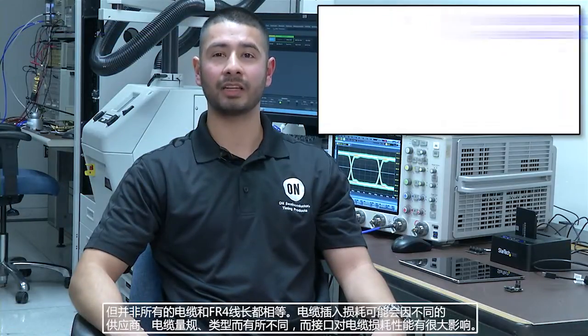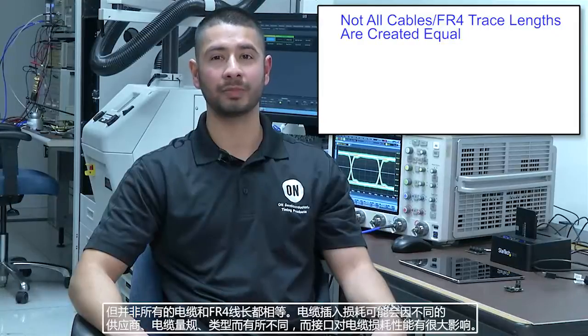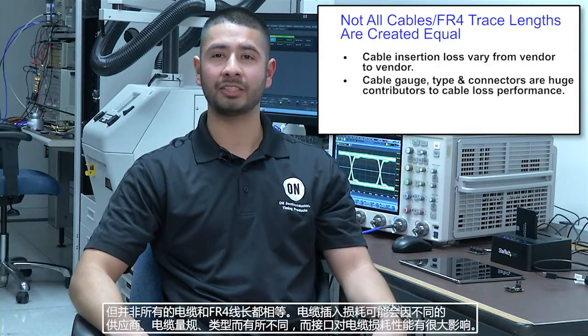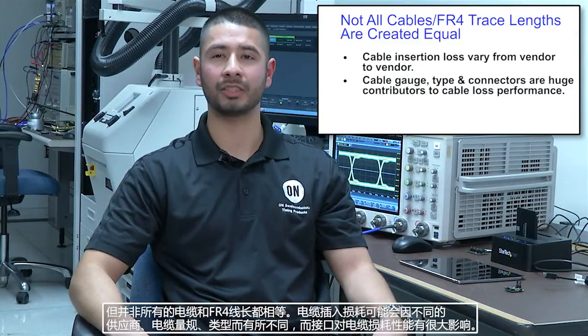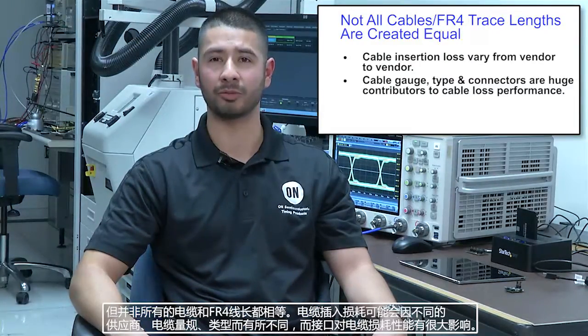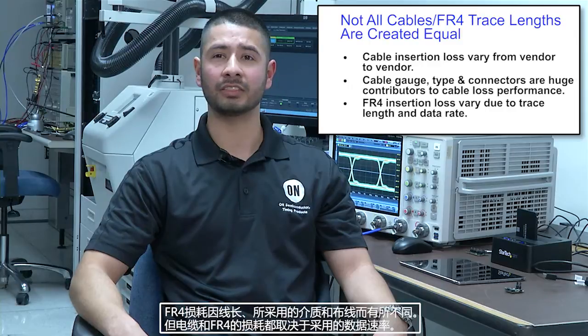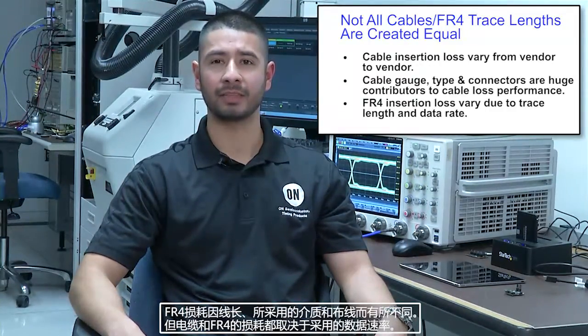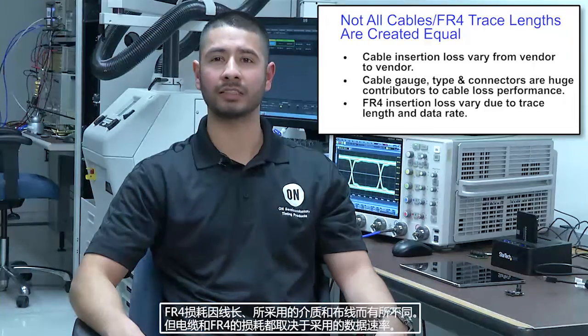But not all cables and FR4 trace lengths are created equal. Cable insertion losses may vary from vendor to vendor. Cable gauge, type, and connectors are huge contributors to the loss performance of the cable. FR4 insertion loss varies due to the trace length, the dielectrics being used, and the routing. But both cable and FR4 losses are dependent on the data rate being used.